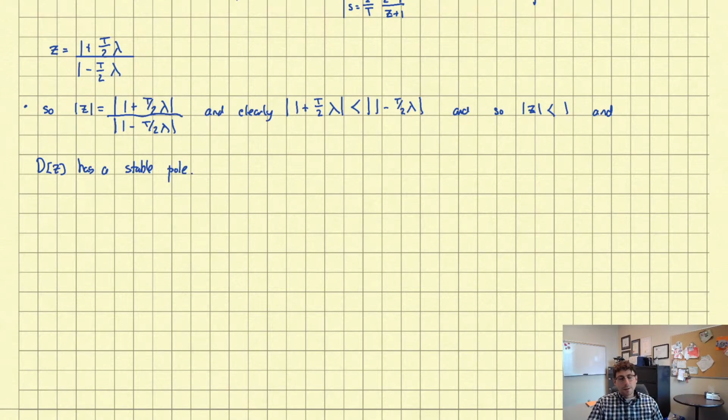One thing that we're going to review in Chapter 6, but this is a reminder here. This is another point where we're using a little bit of ideas from discrete time systems. Stability for a discrete time system doesn't depend on left half plane, right half plane, like it does for Laplace world. It depends on whether or not the poles of the transfer function are inside of the unit disk, in other words, have magnitude less than 1.